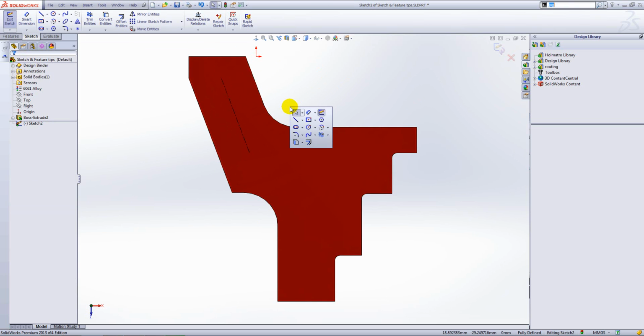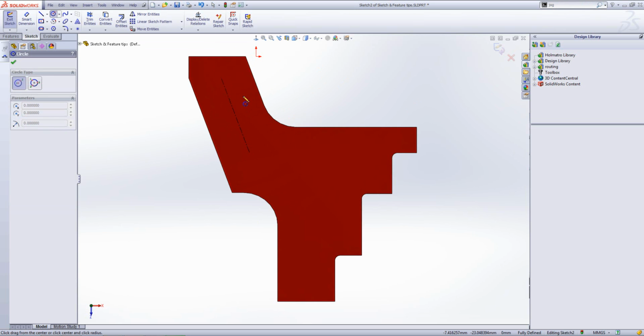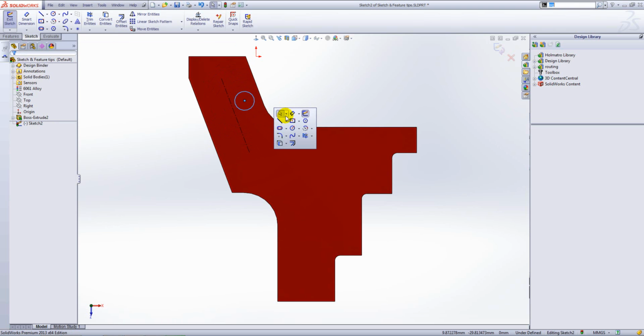Now going to add in a circle, so we'll grab hold of our circle tool and as you are creating a circle, if you hold the shift key, you can snap to various increments, and you can set these increments up yourself. That used with the add dimension tools is fairly powerful. Now I'm just going to place this sort of down randomly, and we're going to go ahead and dimension it.